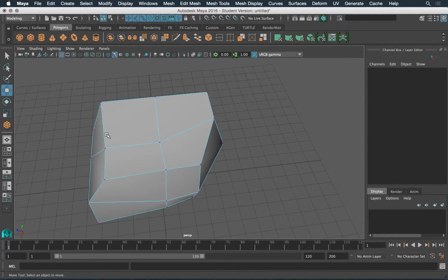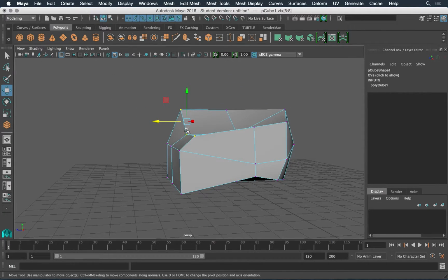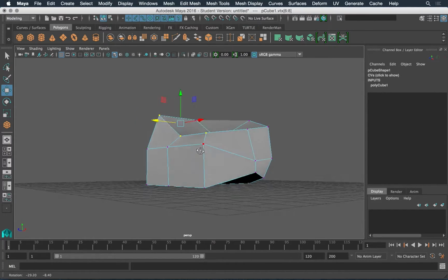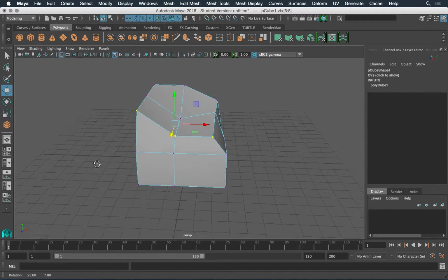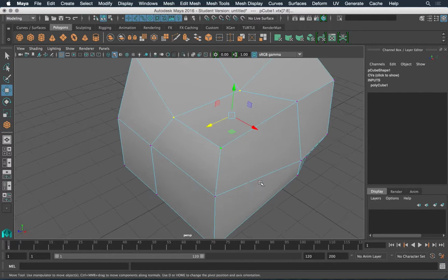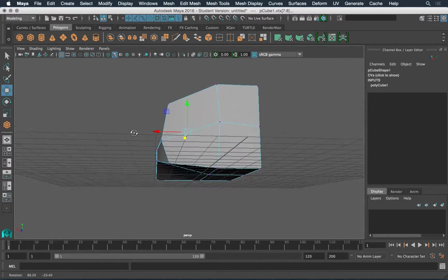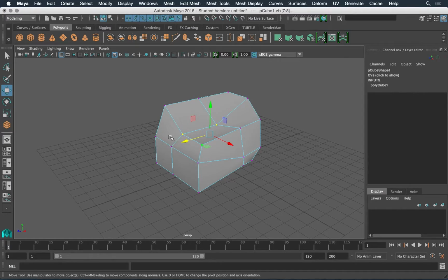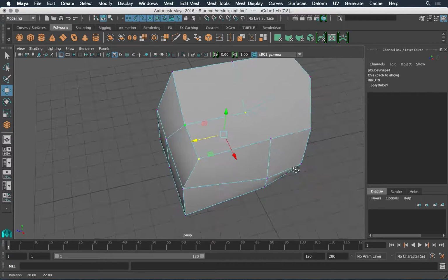Good. You can select more than one. So if I grab one, hold Shift, Shift again, I can grab these three. They turn yellow. It's very easy to accidentally select a vertex on the back side of the object when you're selecting one on the front. Even though you think maybe you off-click by accident and you're not clicking anywhere, you're actually selecting one behind. It's not doing it right now for me, but it's quite a common problem. So before you do anything, just double check that you have what you actually want selected. Faces too, or edges, it's a very easy and common problem to experience.